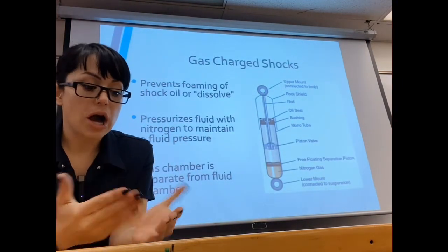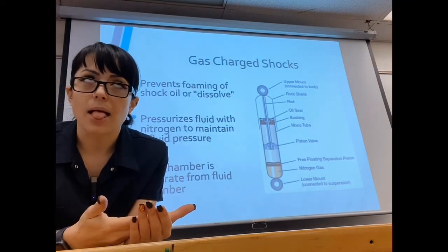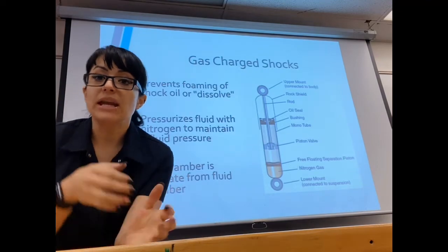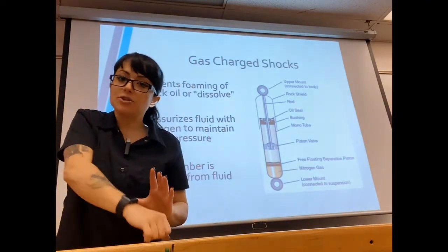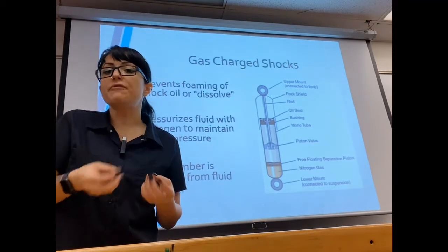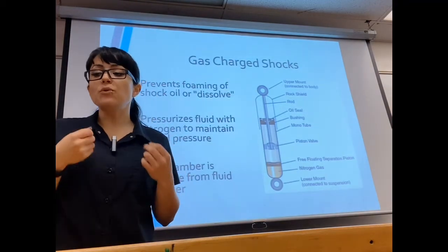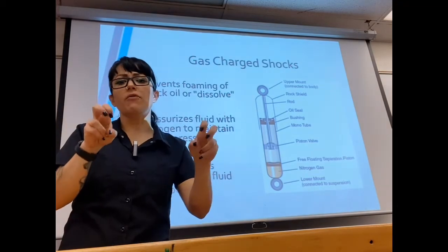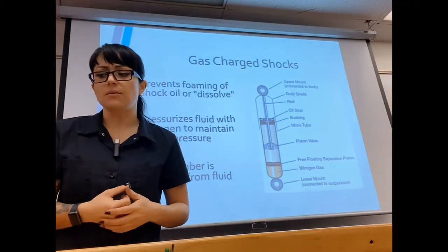This is so in the shock absorber, I'm going to have fluid. And that fluid, if I have a lot of jounce, rebound, or compression, rebound, that movement in the fluid can cause foaming. And we don't want foaming or what they'll call oil dissolve, where we get a lot of air pockets in there.